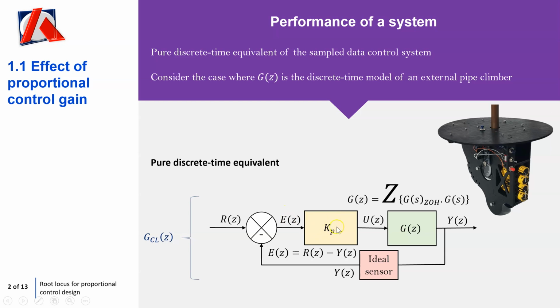The controller, at the moment, we're just going to look at kp, but in a couple of lectures' time, as well as proportional, we'll have integral and derivative. Then here is the control action, which puts more or less power into the actuator, in this case a DC motor, to increase or decrease the speed, or to stop the motor altogether when it has to stop at a specific location. So that's your feedback control system.